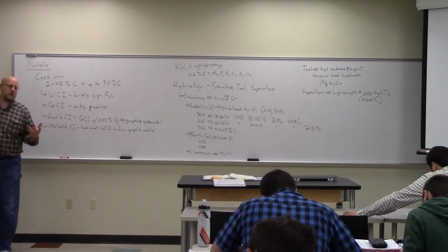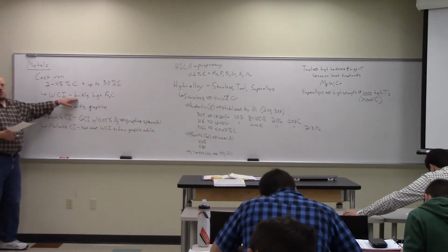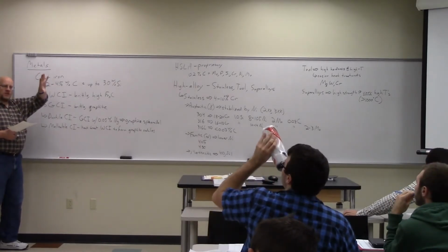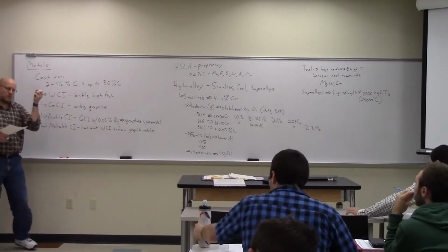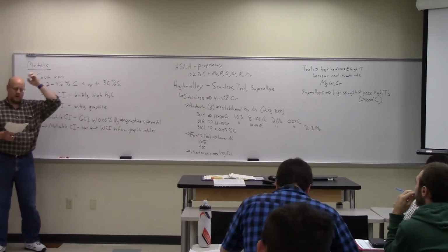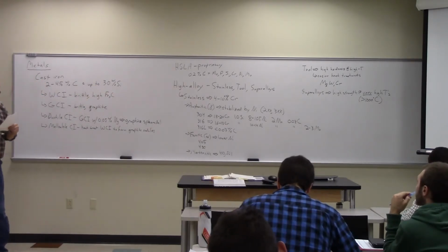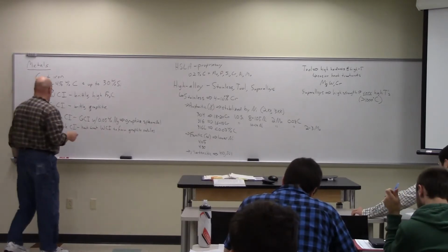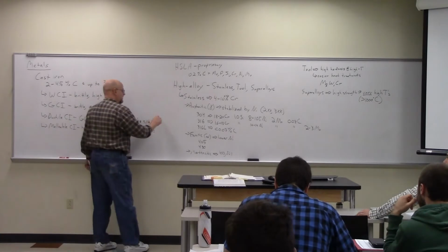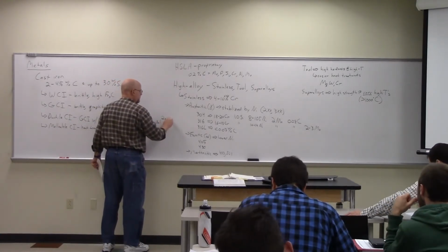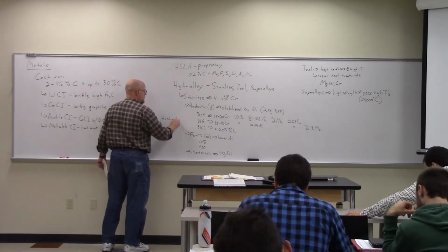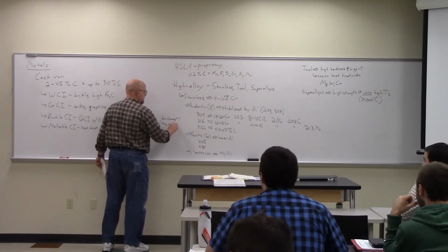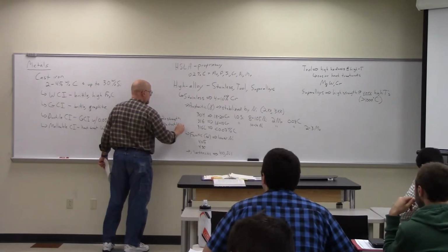So the idea there is it's primarily Fe3C, but we can heat treat it. You know, get it up there, let it sit at temperature so that the Fe3C can achieve its true equilibrium form, which is graphite, and it'll do it in sort of a nodule effect. So ductile cast iron compared to gray cast iron has 2 times the strength, but 20 times the ductility compared to gray.